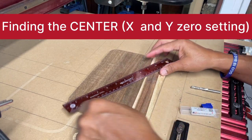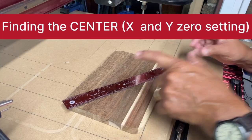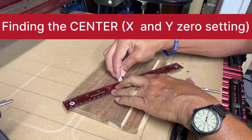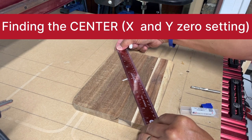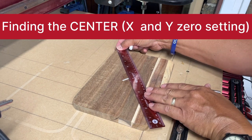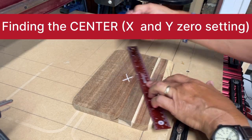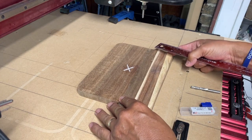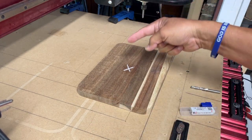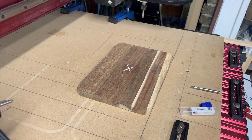You can simply take a ruler and go from corner to corner. Draw yourself a little line. I like to use chalk, especially on this darker wood. And then where your lines intersect, that's the center of your project. And so when I'm setting this up, I'll tape it down here. I'll move my router into the position right into the center, and that will be my XY center.